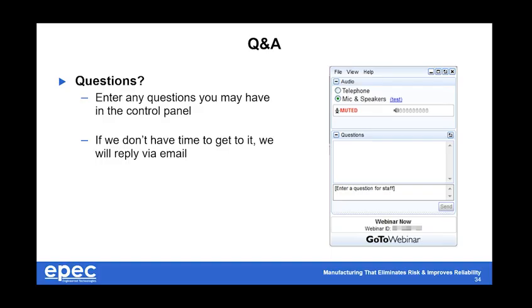Last question we can take here is, we need UL on our product. Can we use your wire in this build to satisfy the testing Intertek is doing? Absolutely. I think actually employing UL wire in your build or in your kit is the preferred way, and something that these third-party testing companies like Intertek are going to look for.